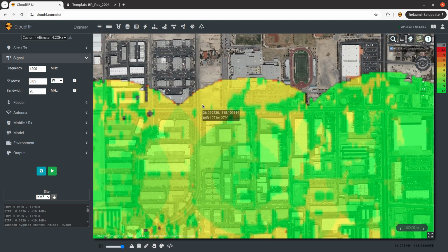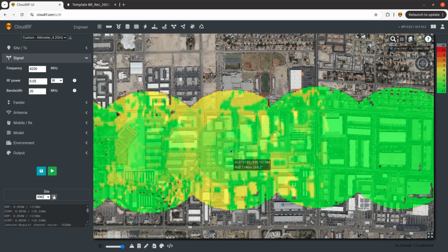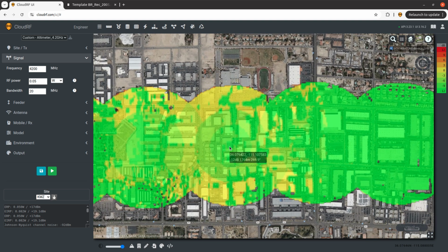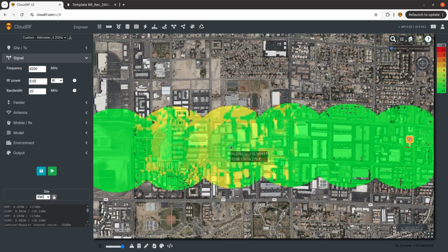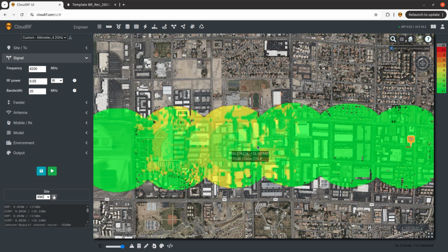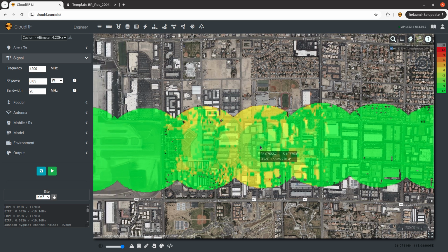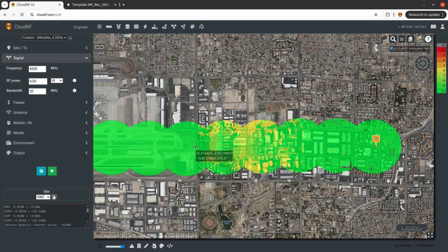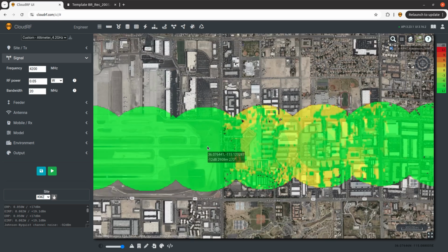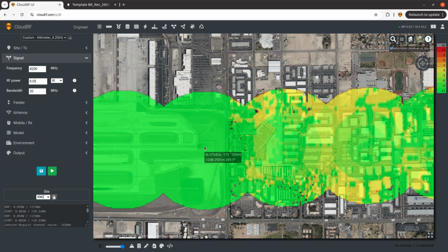Where the signal is weakest, that's where the 5G signal is able to dominate, despite being over 200 megahertz away in the spectrum. It can't dominate directly underneath because that's where the altimeter is slightly more powerful, and also the cell has a very directional antenna pattern. These are antennas designed to serve handsets on the ground, not handsets in the sky. Once we're clear of the cell, the signal is cleaner, and we're able to measure the ground height accurately with a nice clean signal.